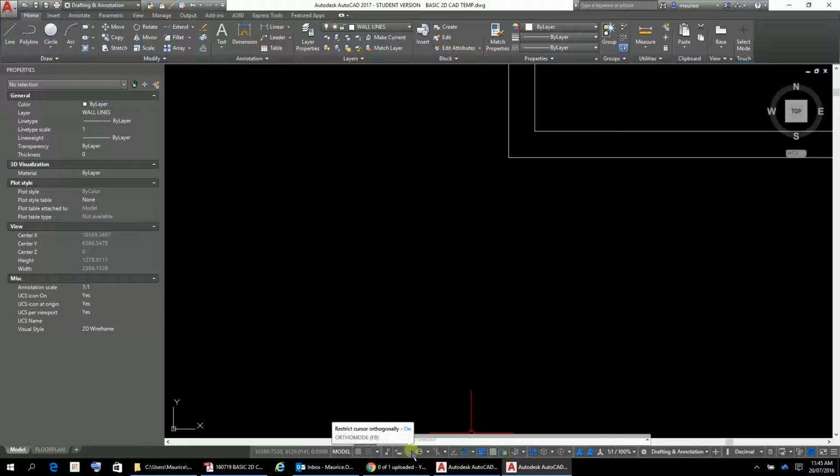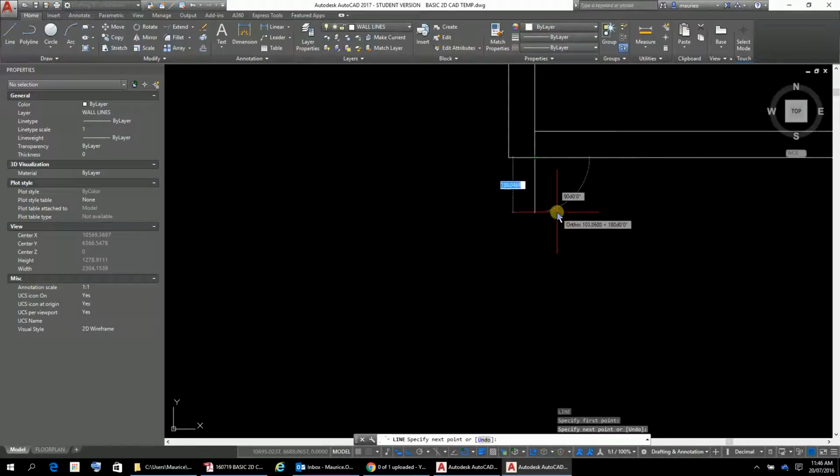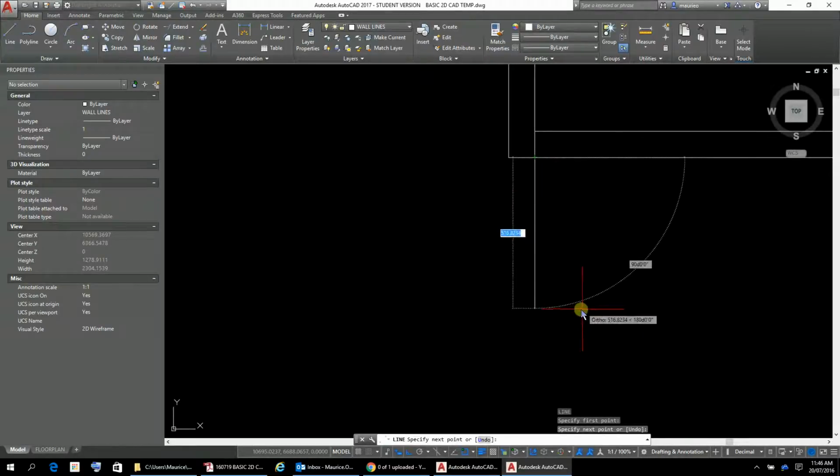I'm not sure whether it's one of these little keys on here, not sure exactly which one. Dynamic input, it's off in this case, but you can turn the dynamic input on as well, which is another helpful little feature. So L for line. With dynamic input, it's telling you, giving you lengths and things as you go, giving you your angle and what have you there.